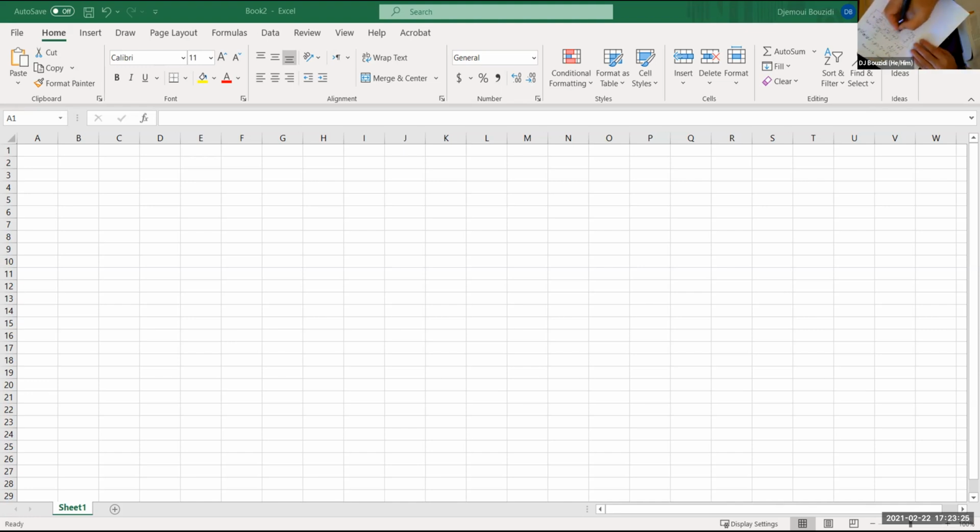Therefore, this answer in here is rho times A minus rho of the water times A, because the volume, if you guys remember, although it's a cube, it's easy to see why. This area is A, that is actually sinking the block, and this height is A because it's a cube, so it's the same thing in here.